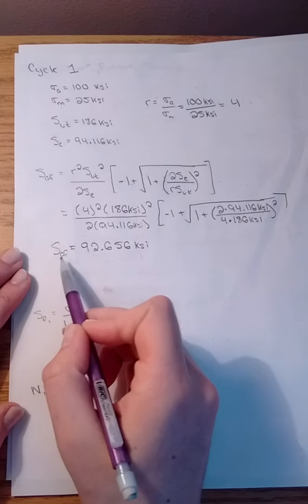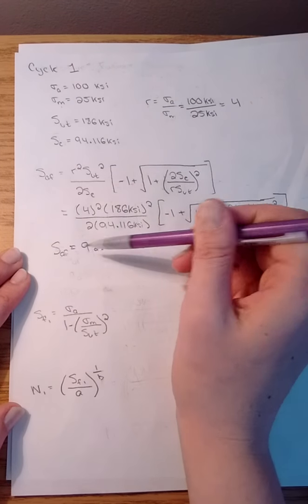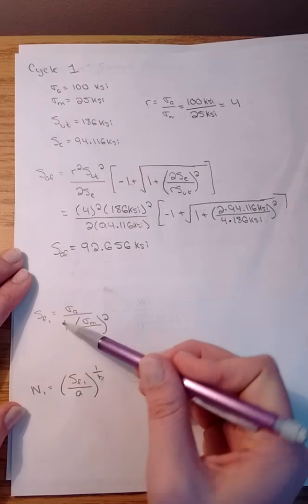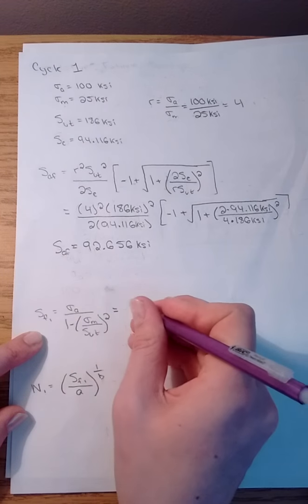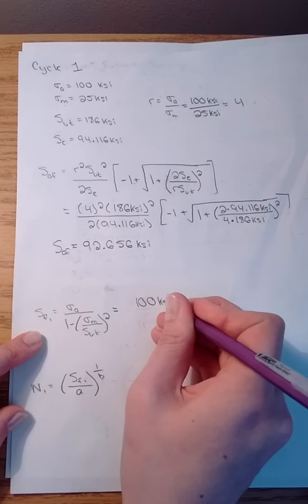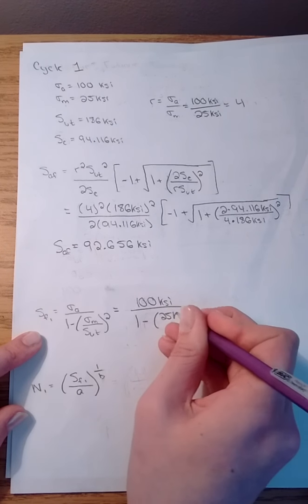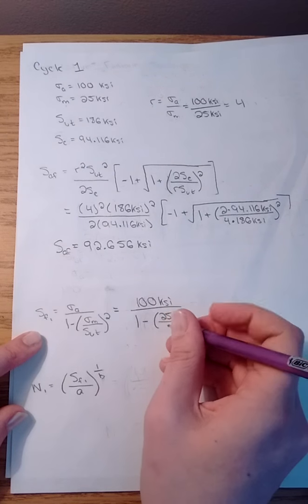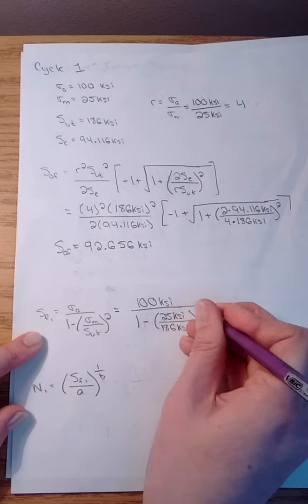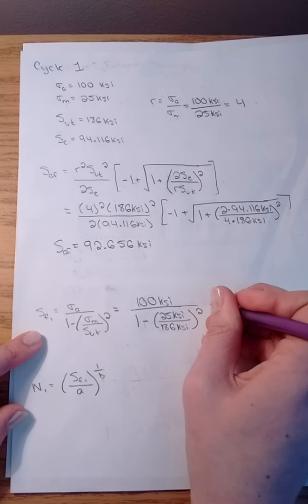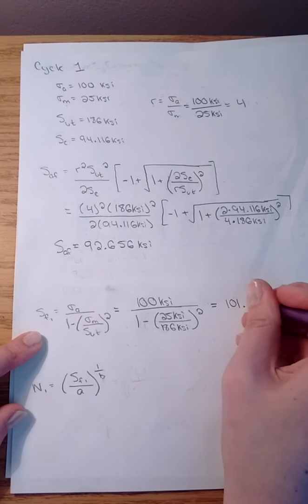Now what you do is compare this value to sigma a. In this case, sigma a is greater than S sub AF, so you continue down with this equation and solve. So it becomes 100 ksi divided by 1 minus 25 ksi divided by 186 ksi squared. And this comes out to 101.84